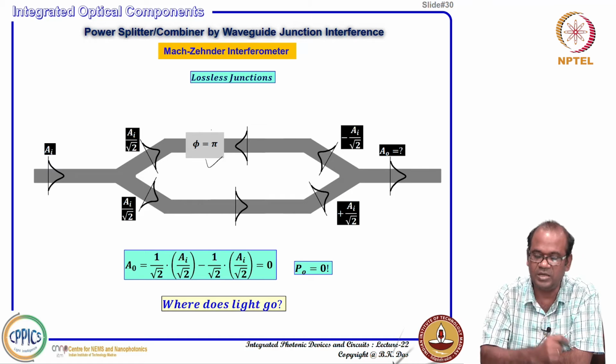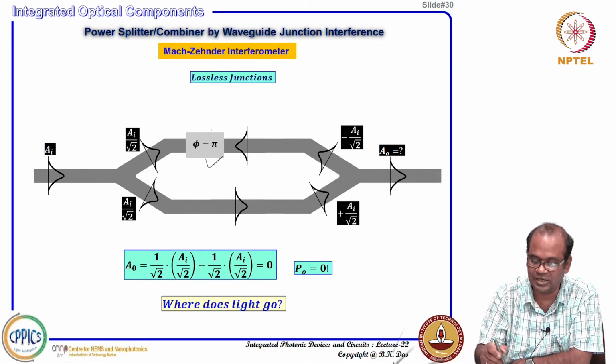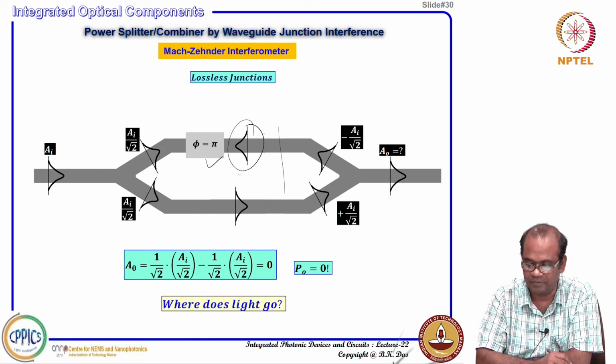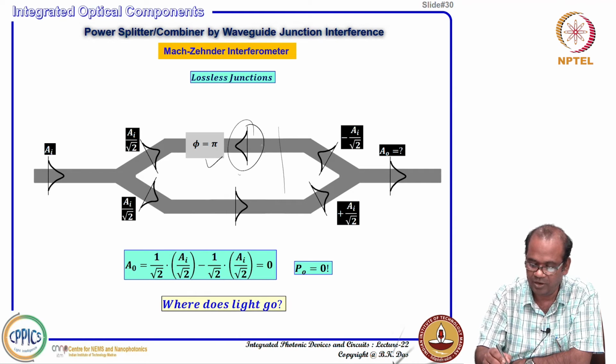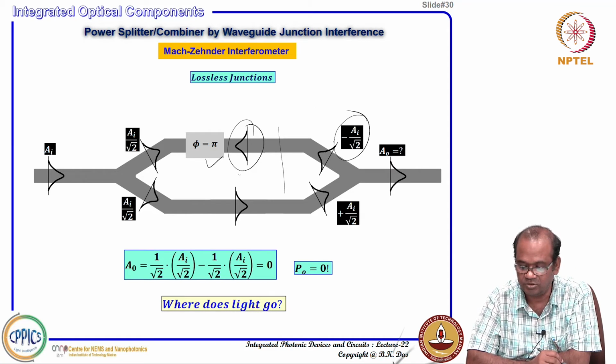I discussed that earlier, when the other junction was not there at that time. With the pi phase shift, with respect to this one, I have just shown the field is flipped, the field distribution, and when it is propagating, relatively everywhere it is flipped and comes out like that. Now, this flip means I can just say that a pi phase shift means a minus sign will be introduced.